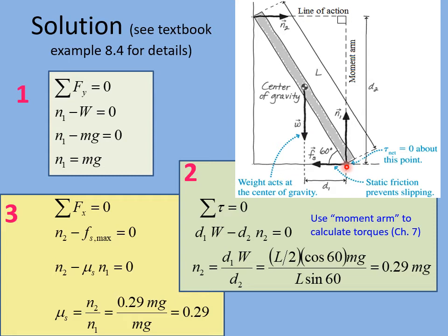Now the reason for doing that is there are two forces there, and neither of those are going to generate any torque if we choose our pivot right here. So again, the choice of pivot is arbitrary. You can pick a pivot anywhere, but this will simplify the problem. This is a tough problem, but it makes it a little bit easier by choosing this point as a pivot.